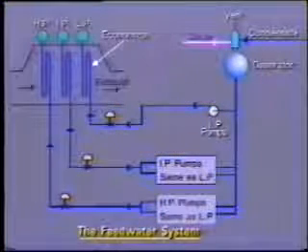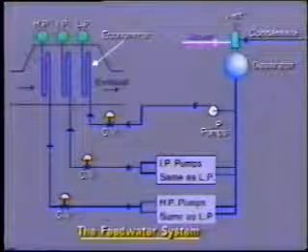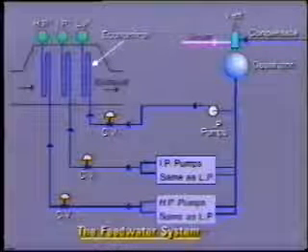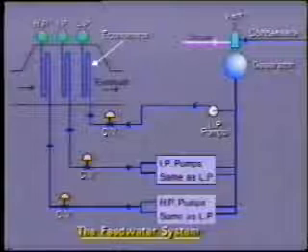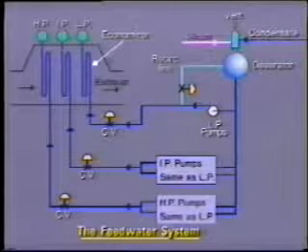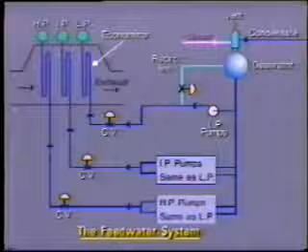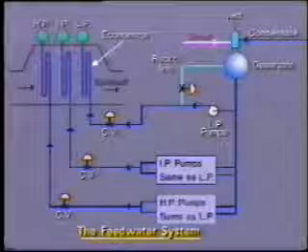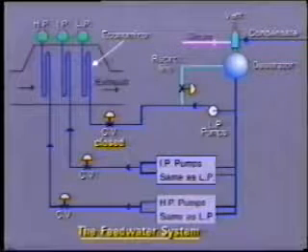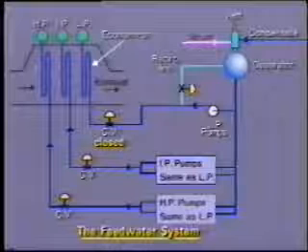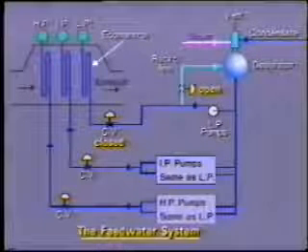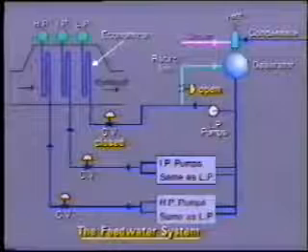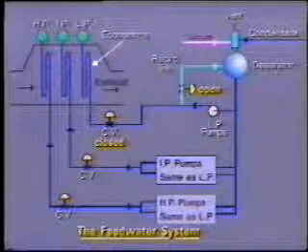In each of the circuits, a feed water control valve is installed to regulate the flow of feed water and maintain the correct level in the drum. On each feed pump, a recirculating line is installed so as to maintain minimum flow through the pump, in the case that the feed water control valve closes, perhaps due to high water level in the drum. The recirculating valve opens automatically when the flow through the pump falls below a minimum value. It recirculates water back to the de-aerator.